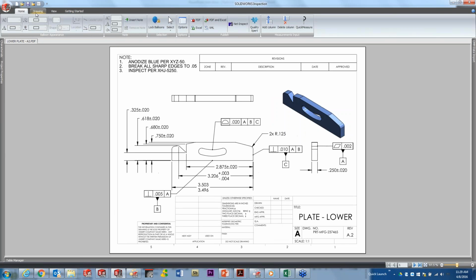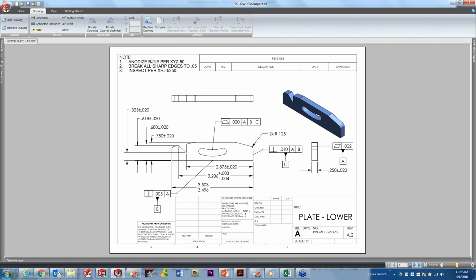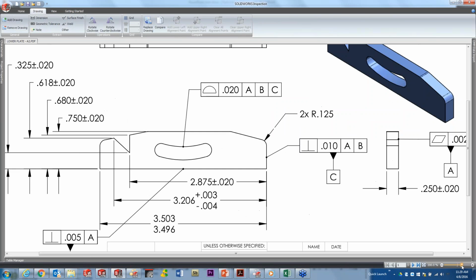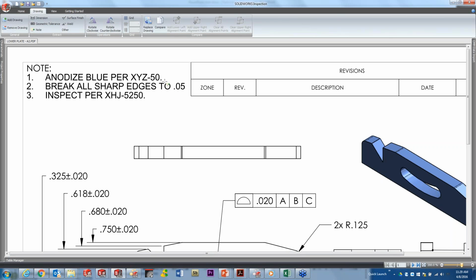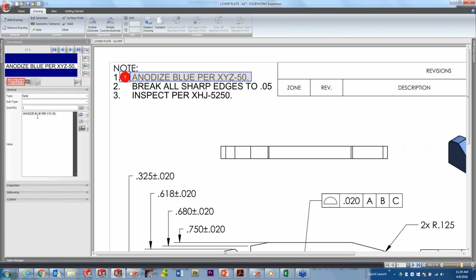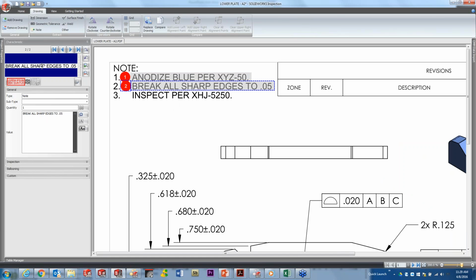I can use it to capture anything that I might want on the drawing, so if I'm just grabbing note information here, I might go up to the upper corner and just simply window select. Now it utilizes optical character recognition. So as I window select entities, you'll notice that these feed back directly into our characteristics tab, but it also automatically reads the text that's within our capture window, and it's pretty good at this.